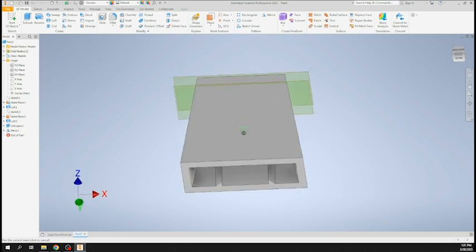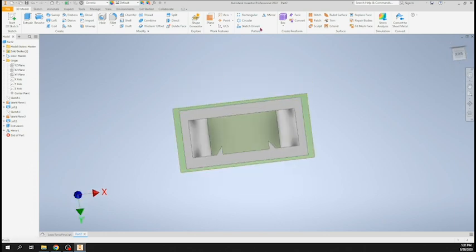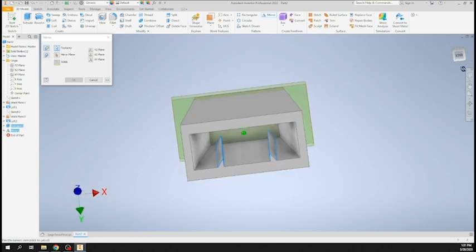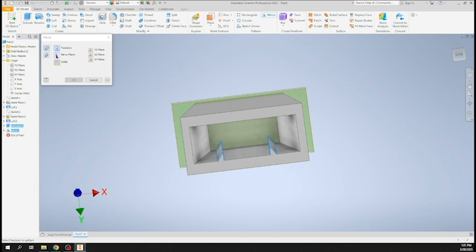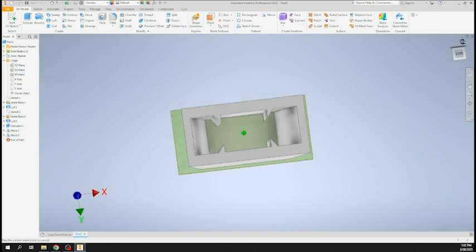All right, we're going to actually do that one more time. We're going to copy both of those features. So hit mirror again, and then click on this triangle and this triangle. Make sure you have both of those selected only, which I do. And then hit the mirror plane in this menu, click that, and then come over here and find the bisecting plane that goes across, which is the XZ. Click it one time and hit OK. And now those features have found their way over to that.